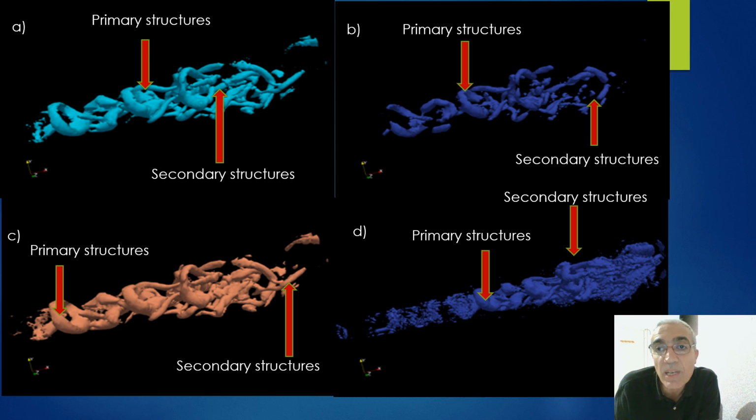It can also be seen that the vortex structures are almost the same based on the Q criterion and the lambda 2 criterion. Indeed, these two quantities are related by Q equals minus 1/2 (lambda 1 plus lambda 2 plus lambda 3). This means that if Q has a positive value, the mean eigenvalue of lambda is most likely negative.